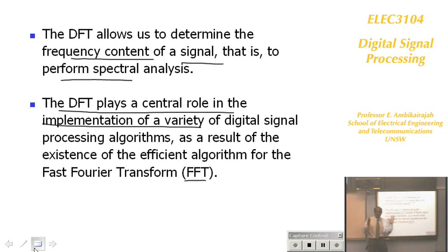So, summary. You've got a discrete sequence. You want to find out what frequency content it has. You've got two options. One is to write a big equation and solve it, and you get x theta, which is a continuous value. Or you say, no, I'm only interested in the frequencies available in it. So you use discrete Fourier transform, which tests only certain frequencies, whether they are available, and tells you the amplitude and the phase. And the way of implementing it is the fast Fourier transform technique.